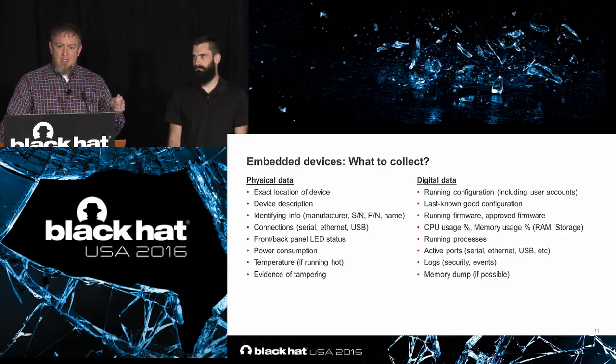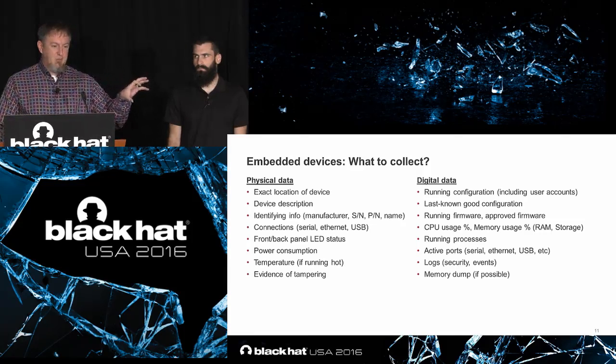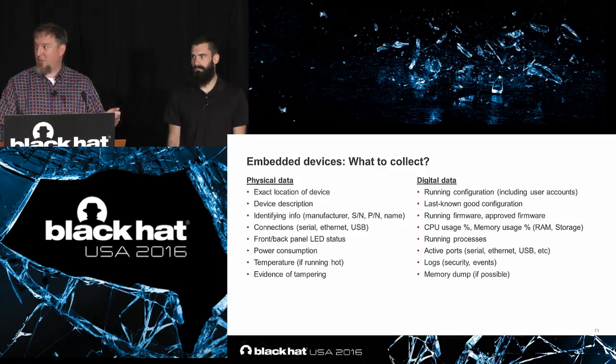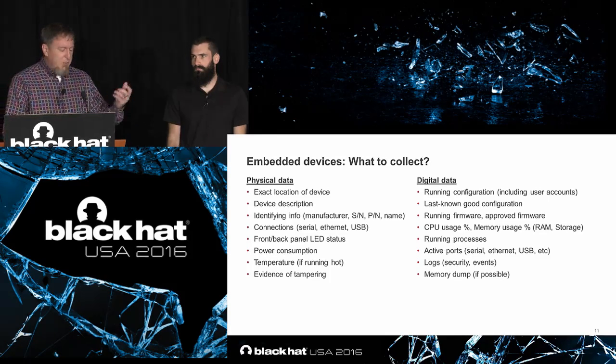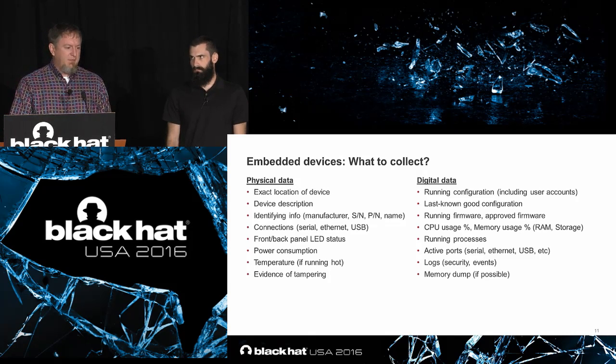Mark Fabro talked about an event where there was a Windows HMI in a combined cycle power plant that they noticed with the FLIR camera, one of the boxes was really hot compared to the others. And then they found out that it had malware on it. So you can use out-of-band ways to detect and collect information. And evidence of tampering. So physical access is important. You need to keep tabs of that as well.